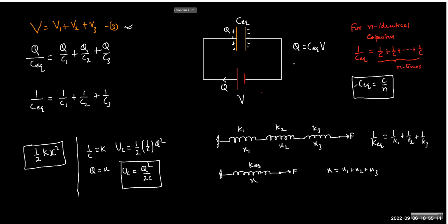So using 10, you can create one. You know that to create a smaller value, I need to connect in series. But now you want to increase. Let's say you want 2 microfarad. So you make two such layers of 10 and join them in parallel. Then it becomes 2 actually.